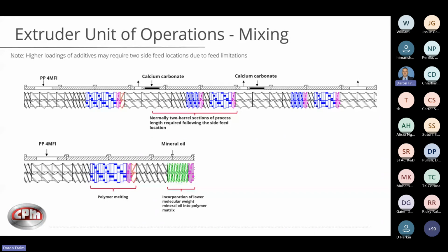If you're bringing in 40, 45, 50%, you may overcool that polymer, stress it, and it may even solidify, and you can, of course, over torque your machine. What you'd have to do is go back upstream to your first melting section and increase that more in its aggressiveness to raise that polymer temperature to compensate for the drop in temperature when you're adding the calcium carbonate.